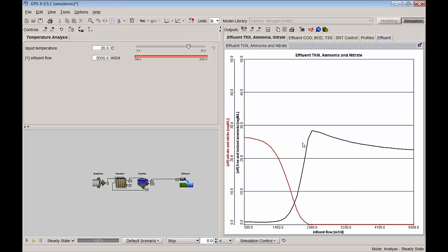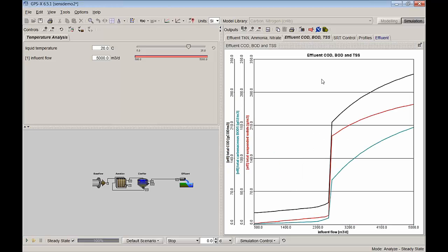So this is a nice way to do that kind of analysis, is to be able to set a low point and a high point and then run a number of simulations, get all those results back, and be able to look at that nice and cleanly for this particular relationship. Now you could, of course, go back and try this again. It's all sensitive to whatever the parameters are that you've set. The ones that you're not making part of your sensitivity analysis are still playing a role here. So you'll get a different answer here if I waste differently or if I do it at a different temperature and so on. So I plotted other things here too as well, and whatever graphs you make, they will all be filled out as part of this sensitivity analysis.